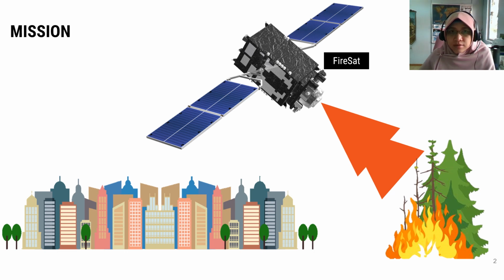Okay, we start deriving payload requirements by returning to the mission statement defined earlier. The mission subject should be clear in the first place, as indicated by the objective, users, and operation concept. We define the subject of the mission to be a natural or manufactured object or phenomenon that the payload will sense or interact with. We characterize the subject by such things as its colors, size, shape, temperature, chemical properties, or frequency.